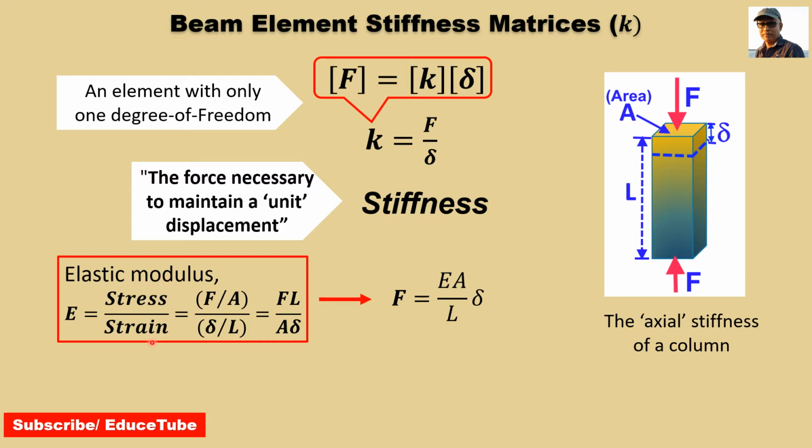As we know, elastic modulus equals stress by strain, and expanding that we can write force equal to EA over L multiplied by delta.